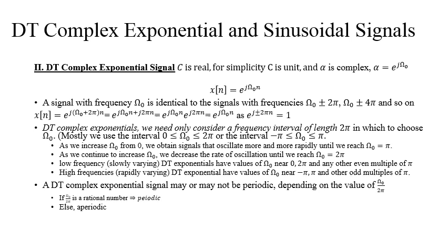Let's say we have a signal x of n equal to e power j (omega naught plus 2 pi) n. This can be simplified: e power j omega naught n plus j 2 pi n. If we split it, we get e power j omega naught n, which is your resulting signal, times e power j 2 pi n, right?